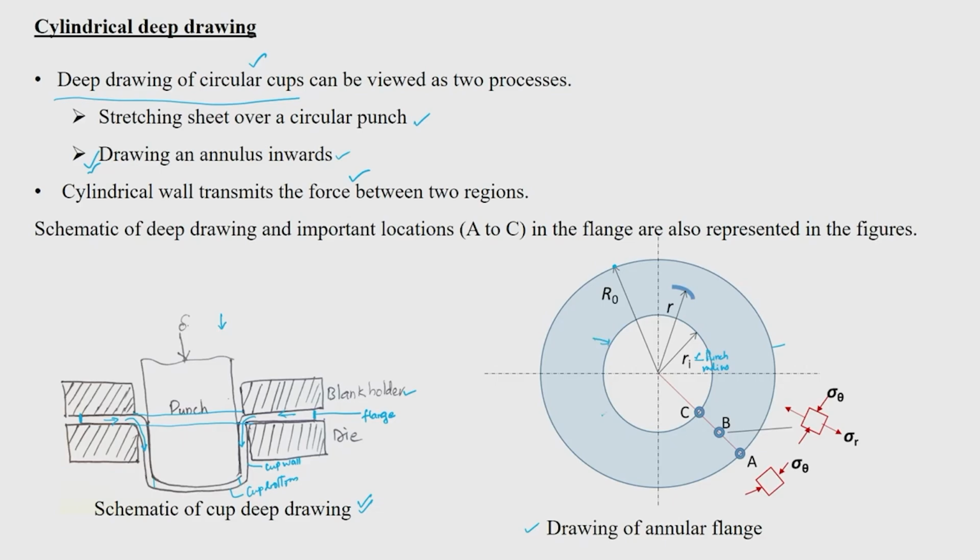So this part is actually going to move inwards, so that it forms a cup. There has to be an appropriate diameter or radius of the sheet because of which you can form a successful cup. A larger blank or a smaller blank may not be sufficient to make the actual cup which we want. So we have to keep that in mind.